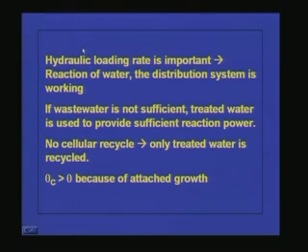But if you provide a series of biotrickling filters, what will happen? One will be giving a particular efficiency. From that one, the effluent is going to a second trickling filter, that will be removing a considerable amount of organic matter, whatever is present in the system. So as a result, what will happen? The effluent coming out of the series of treatment units will be having better quality compared to a single unit. So whatever I have discussed now, it is written here.